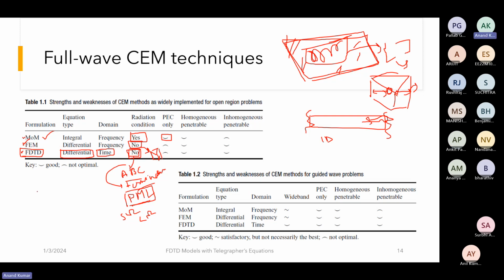In this particular course, we won't be using Mur's or absorbing boundary conditions. We'll terminate them with load and source impedances. We'll solve voltages and currents at the end, and then modify the last node such that it includes a resistor or inductor, so that we can terminate the circuit with, for example, a 50 ohm or 100 ohm load, so that we have that flexibility.